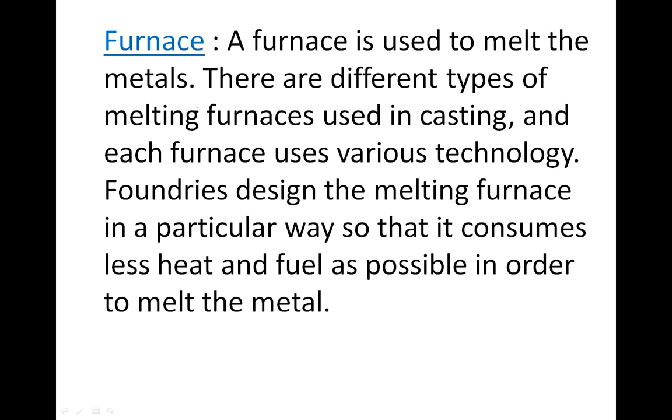Today we are going to discuss the furnaces used in metal casting. There are different types of furnaces used in a foundry shop. The furnace is an equipment used to melt the metal, and different furnaces use different technology. Some furnaces use coke fire, some use oil fire, some are gas fired, and some use electricity in order to heat the metal and convert it into molten form.